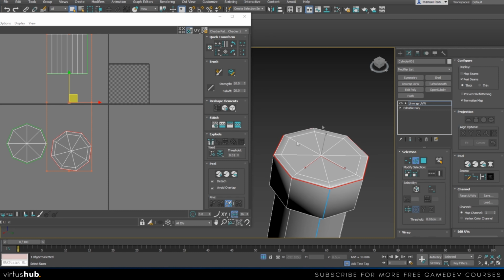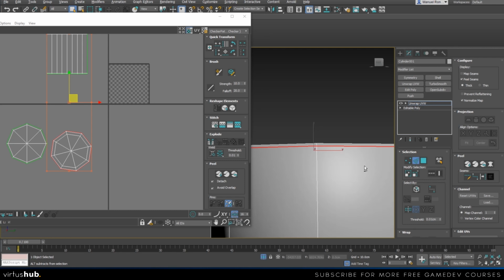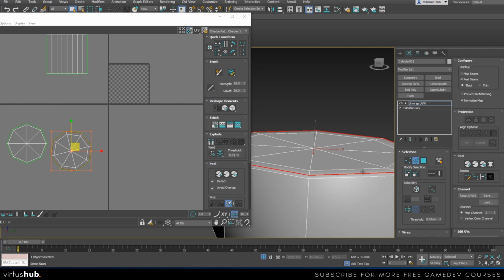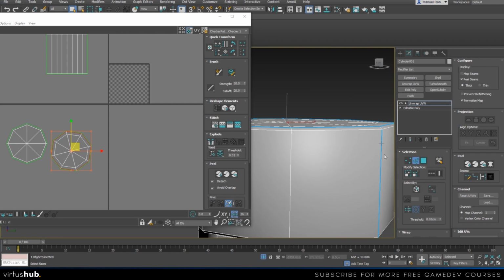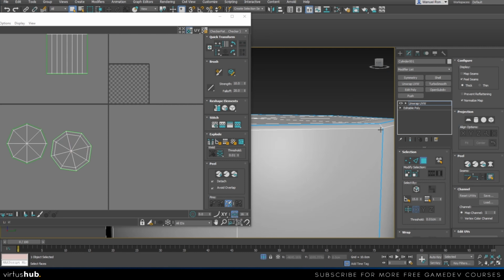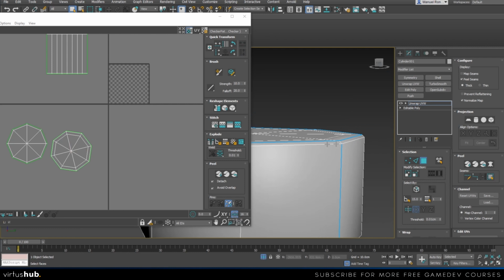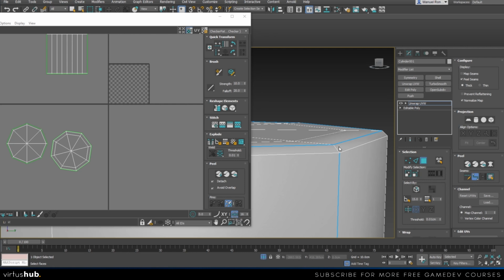So double click would select your whole loop, and what we'll be doing here is, let's say not here, let's do it here. We'll use this button here that says convert edge selections to seams. Right now it's getting a little bit off screen, but that's what it says. I'm going to click on it, and as you can see, that turned blue, and now we have a seam over there. So let me just show you real quick how this is going to look. And I think I missed the seam over here. I'm just going to create it.